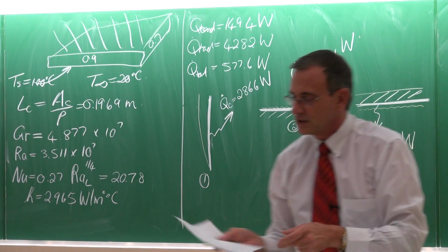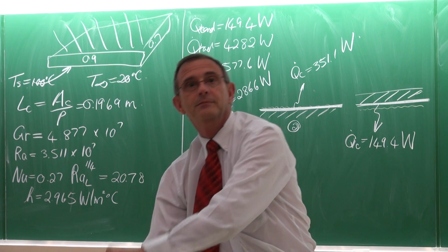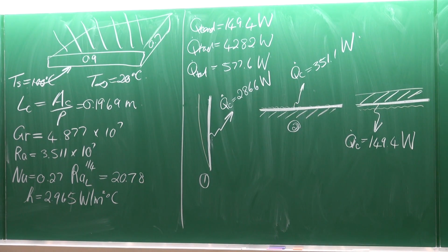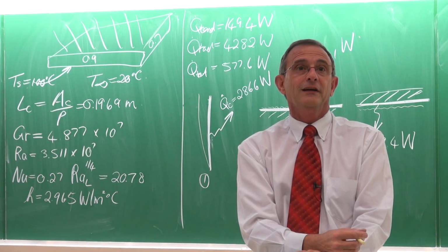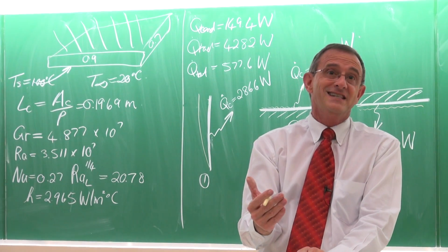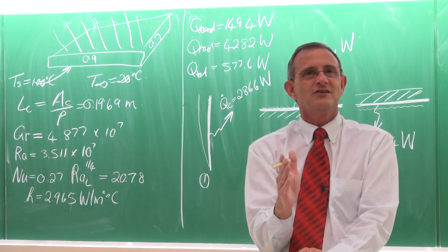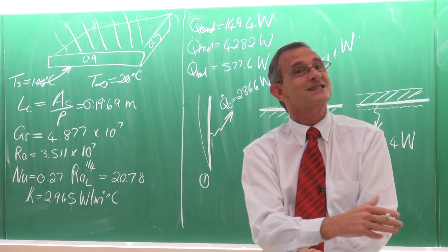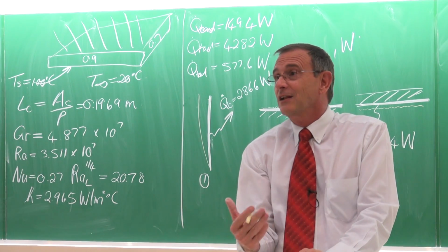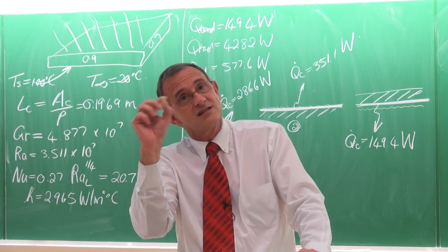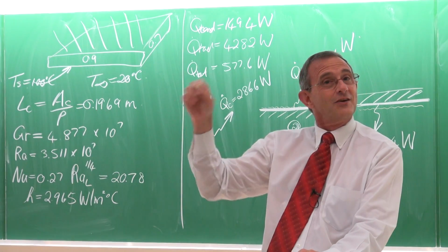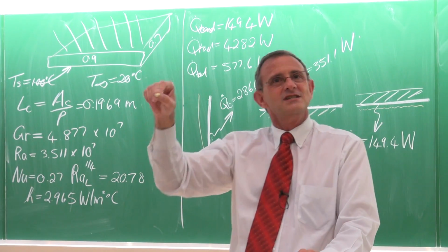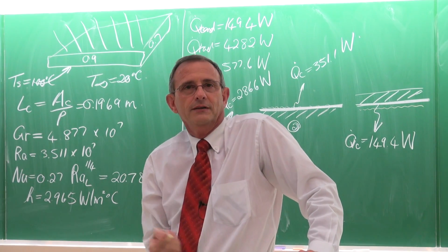Any questions, ladies and gentlemen? Yep. So what if the Rayleigh number is outside that? Yes, if it's outside, then you have a problem, and then you have to go to literature and get values. Some of you may end up in the exam where you're just outside the range. Now you wonder, what do I do now? Because there's nothing else, you will have to say, I realize this is outside the range, and I realize most probably I've made a calculation error. So I know I shouldn't actually use it, but because there's nothing else, I'm going to use this correlation, then it's fine. Okay.